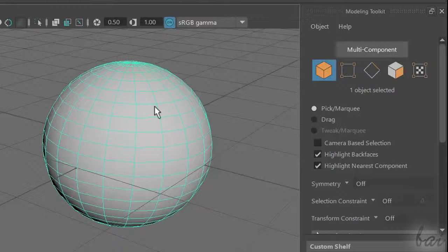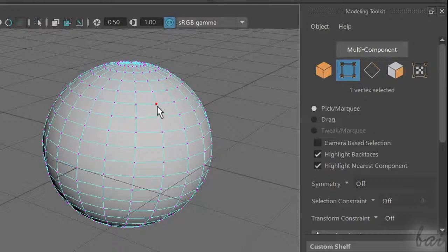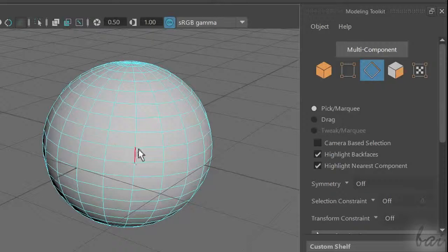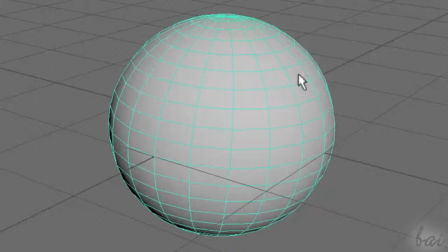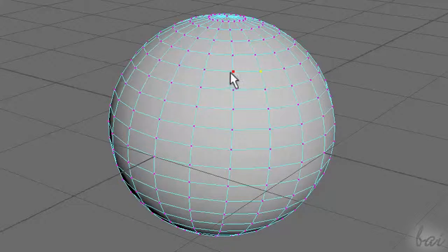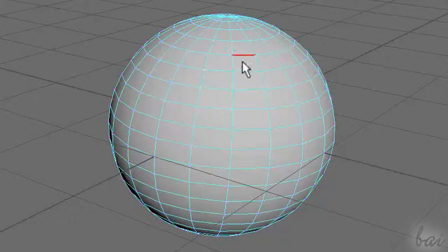Selected objects are shown in green. Use the second button to select vertices. Use the third one to select edges. The fourth one is used to select wall faces. Vertices are represented as red points, and edges are always in blue color.